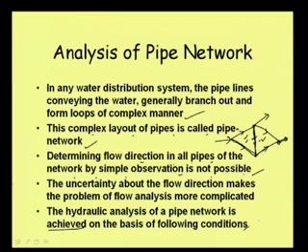Hydraulic analysis means, say, when a discharge Q is coming and we want that Q1 discharge should be flowing in this direction and Q2 should be the final flow, then our interest is to know how much will be the flow in this particular pipe, or in this pipe, or in any of the pipes. Then we may be interested to know what will be the head available at this point. Suppose we want a discharge Q at this point, but this discharge will have to be raised to a certain head. Then our interest is to know how much head will be available at that point. So, that is also one of our interests.